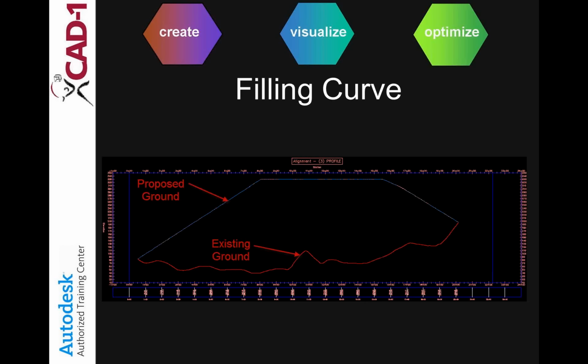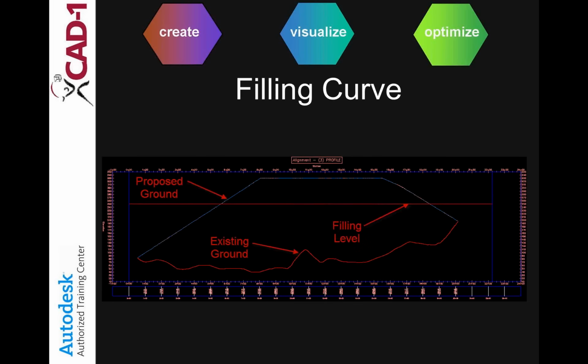In this case, I just did a quick cross-section through it. I've got the proposed ground, that's the blue line, and I've got the existing ground. And what we need to know is, at this specific level, what is the volume between these two surfaces? Now, as you can see here, I can't just simply do a volume calculation between here and here.